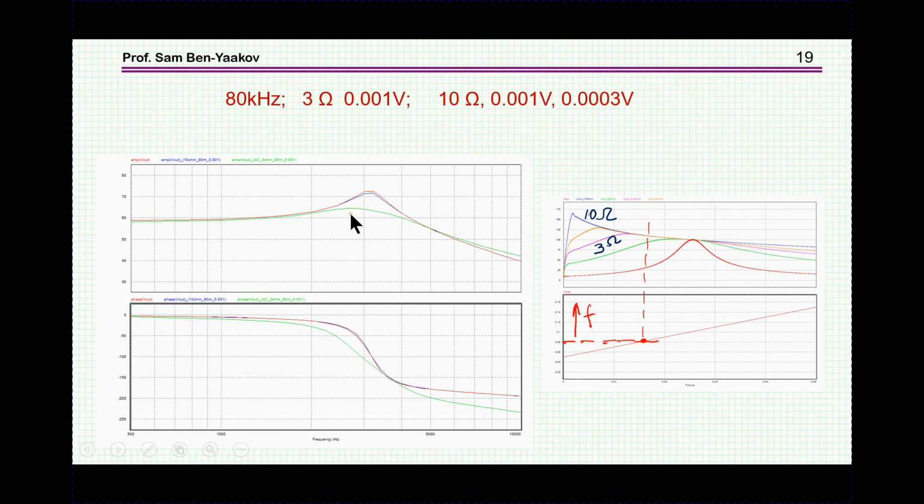So if we look carefully here, we see two carriers which are fairly close. This gives me assurance that I'm in a good excitation value, because if the excitation would have caused distortion and harmonics, these two would be different.